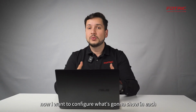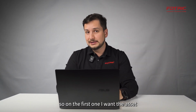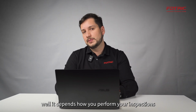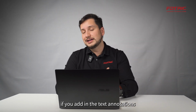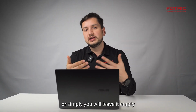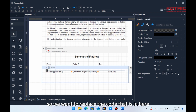Now I want to configure what's going to show in each cell of that table. So on the first one, I want the asset. Where's the asset information going to come from? Well, it depends how you perform your inspections. If you add the information of the asset on the tag, then you want to select that information right here. If you add in the text annotations, when you take the picture, you add a note, then you can do it there. Or simply you will leave it empty and you will manually input that information from your paper record. So let's say that we're going to use the text annotations. So we want to replace the code that is in here.